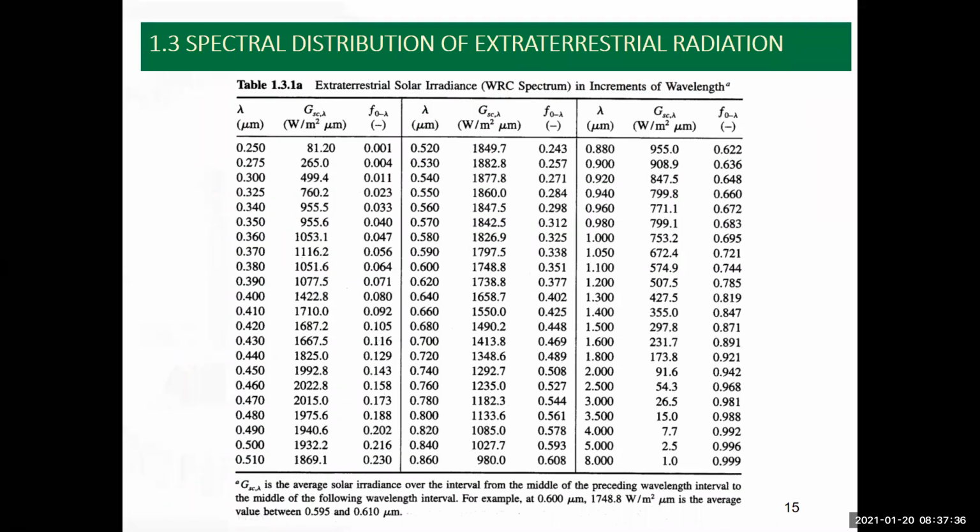And we have seen a table indicating the amount of the radiation, or what we call the monochromatic radiation, the thermal radiation at a specific value of the wavelength. Actually, what is given here is not at a specific value of the wavelength, but a subtotal emissive power, or subtotal irradiation, provided for an average value within a range.